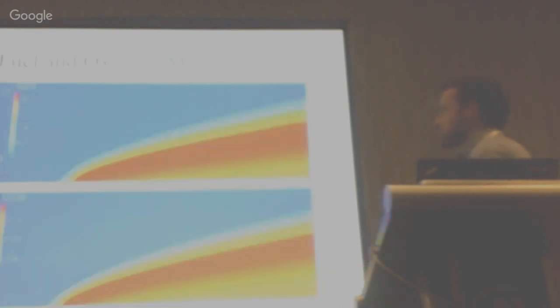So here are the fuel and oxidizer mass fractions, and this really describes how this is a diffusion flame. The first case was not limited by diffusion at all; it was limited by chemical kinetics. That was it: how fast can it burn? This one you can see we have methane that's getting increasingly dense as you march down the plate, and you have oxygen that exists only away from the flame front. So in this area, there's no fuel. In this area, there's no oxidizer. And so you're only allowed to combust in this thin region right here, which is limited by your diffusion. So that's why it's a diffusion flame. Sorry, this is the wrong title. This is the creation of your products, your water and your CO2. Pretty similar. The diffusion rates are a little different, which is why they're slightly different.